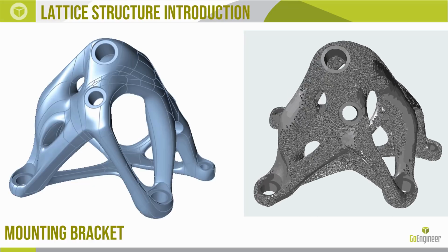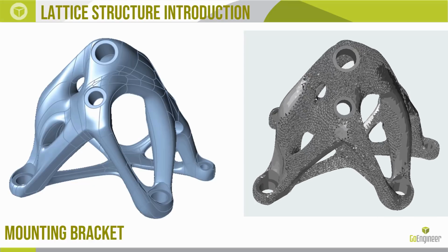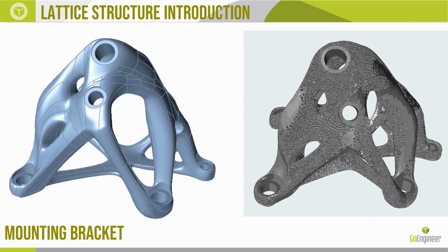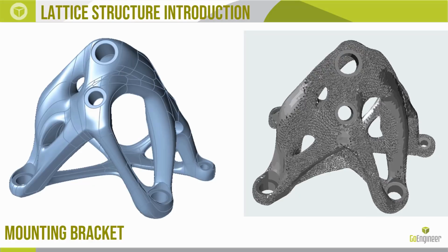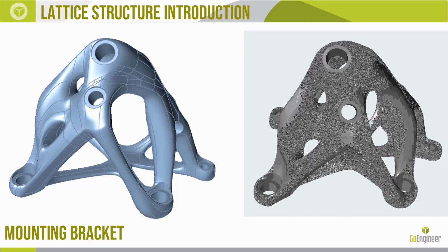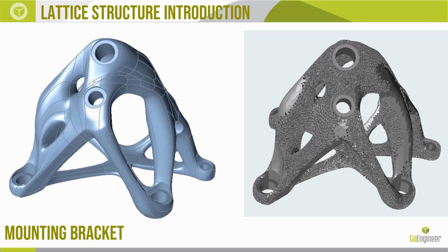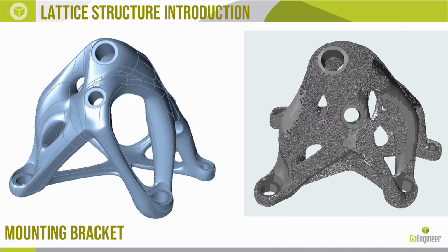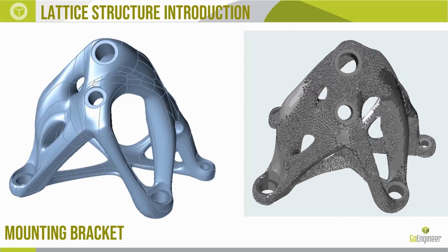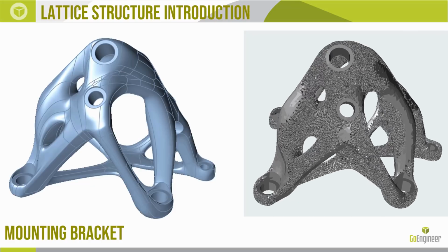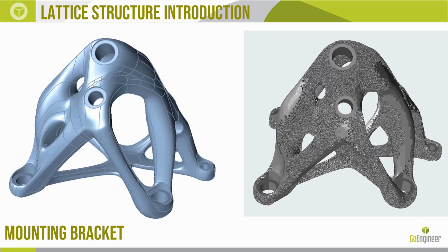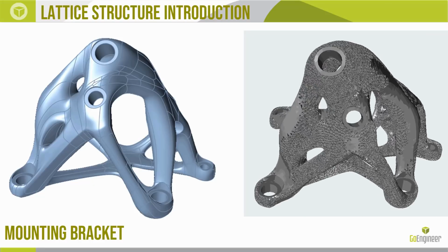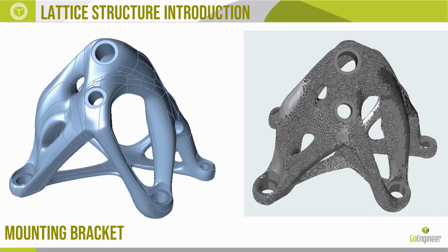The best part about this tool is that it is load-based. So you're not just adding lattice structures in any predetermined location. You're actually adding the lattice structures based on the computer algorithms, and it's looking at where your restraints are. It's looking at what the material is. It's looking at what the connections are, what the different boundary conditions are, and based on that, it is creating a lattice structure that is based on an FEA study or a finite element analysis study.